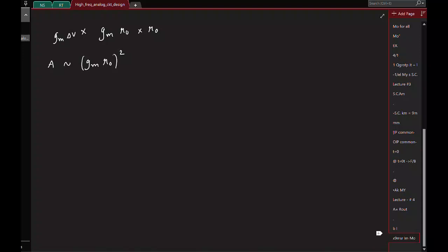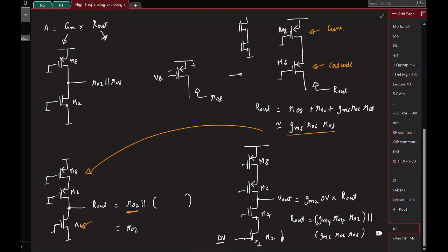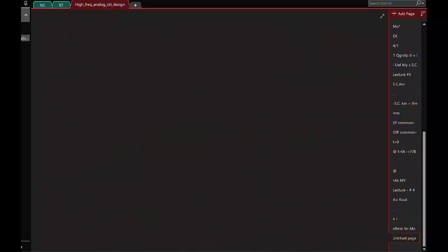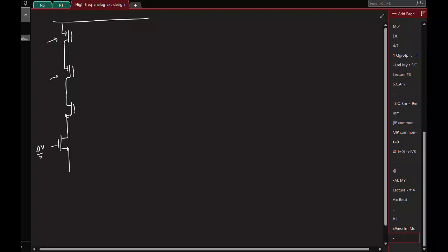So now we've seen it with the single-ended case. Now let's quickly make a differential equivalent. It's going to be the same. So this is a PMOS current source, PMOS cascode, and then you'll have the NMOS cascode and the final transistor where I'll apply the input.